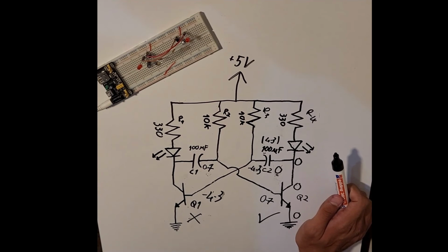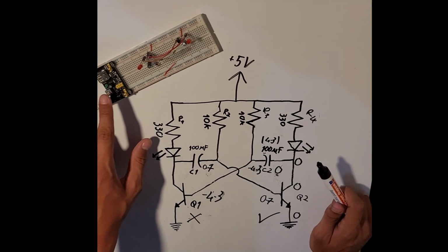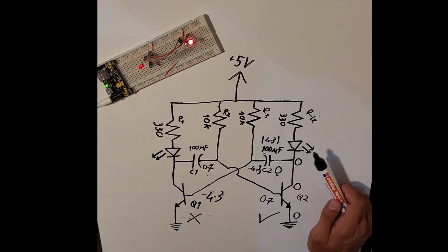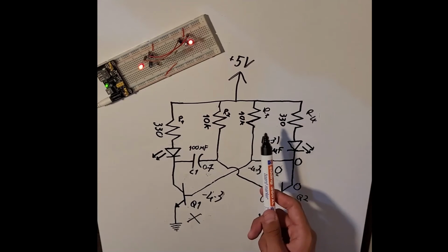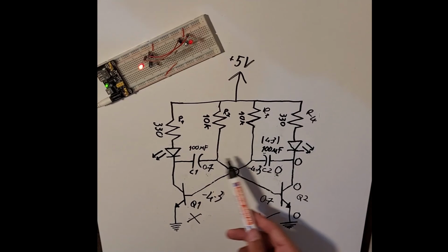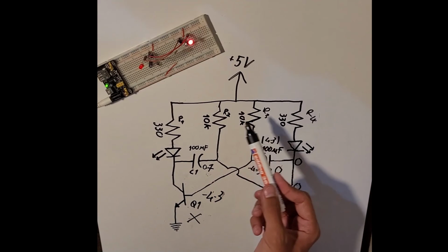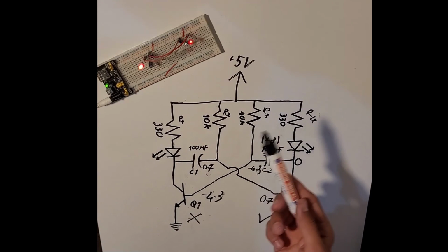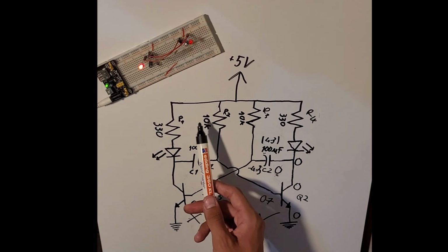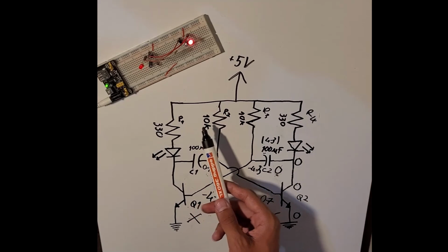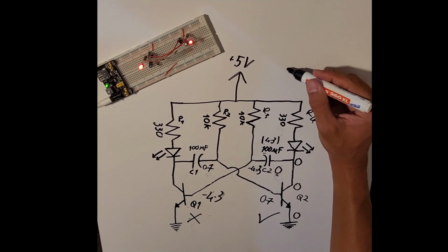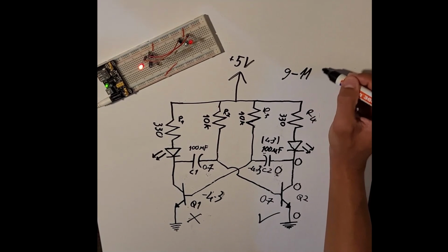Starting off, the circuit can have different characteristics because the components never have the actual value written on them. And resistors usually have 10% or 5% tolerance, which means these 10 kilo ohm resistors can have a value between 9 to 11 kilo ohms.